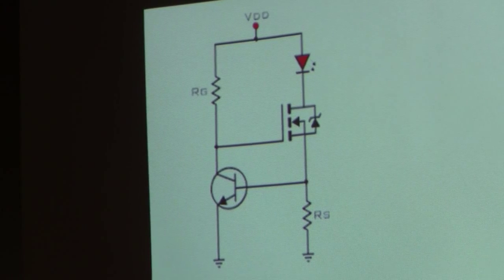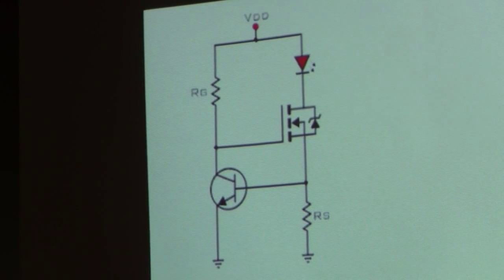Is the gate on the MOSFET there being...? No, it's a nice slow linear thing, because what happens is the NPN here comes on soft. Let's say it's at 0.5 volts. It's thinking about turning on, and then it creeps up to 0.6 volts. Okay, now I'm going to turn on and start stealing a little current.